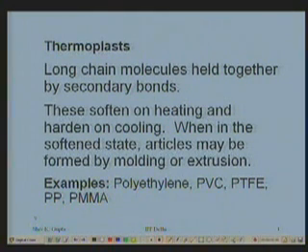Well, you use number of such plastics, thermoplastics. Like you might have seen some of their file folders. Their covers are very soft in summer and they become quite rigid in winter. As you cool, they harden. As the temperature rises, they soften. And in softened state, where they can be below their melting point, of course, it's possible for us to mold them and extrude them and give them the shape we want. So the processing becomes very easy for such materials. Giving them the shape, desirable shape, is quite simple.